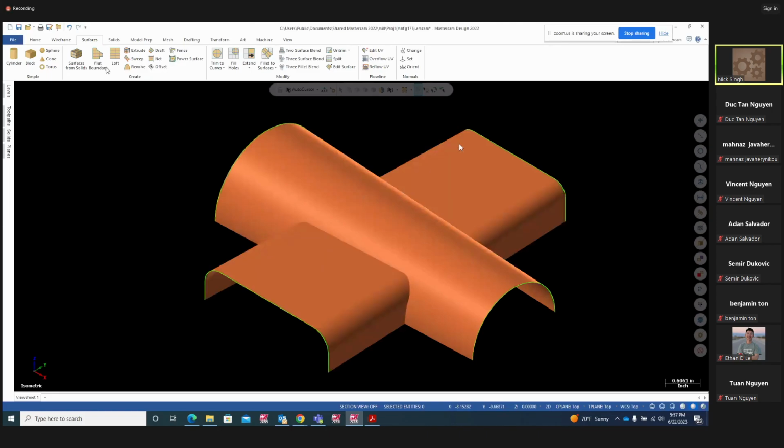To do that, guys, we're going to go into surfaces and we're going to go to the trim option. Click on the arrow, expand the gallery, and you're going to say trim to surfaces. It's under surface. Go here, trim to, not trim to curve. Expand the gallery, and you want to say trim to surfaces. Click that.